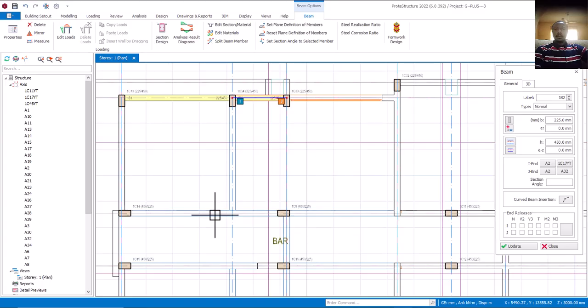So and also this one now. Is that okay? This one now. Okay. So then this one will now be deleted. Perfect. So now this one now we have this one. We cannot leave this one like this, isn't it? So I'll click on this, then remove it. Is that okay? Why am I deleting the column? So delete this one, the beam. Correct. So now take the properties of this and come here and put it here. Correct. So this one now serves as what? As a cantilever. Is that okay?